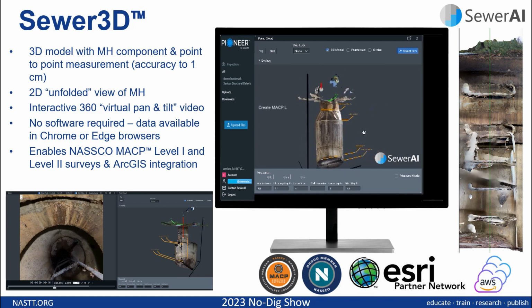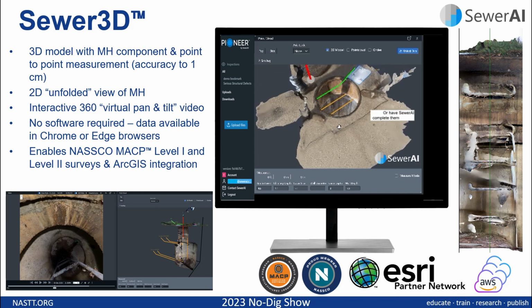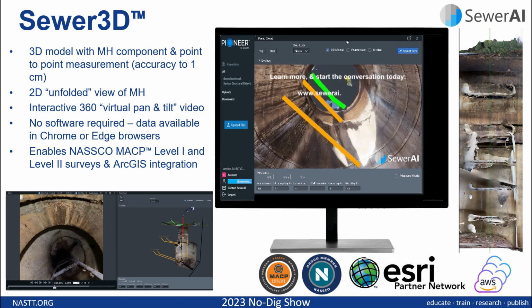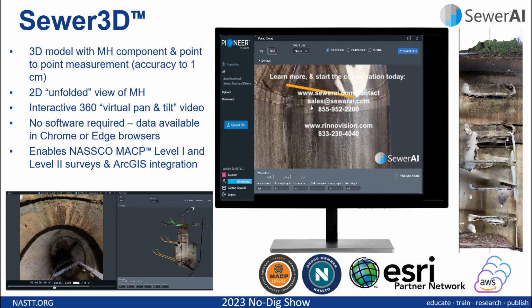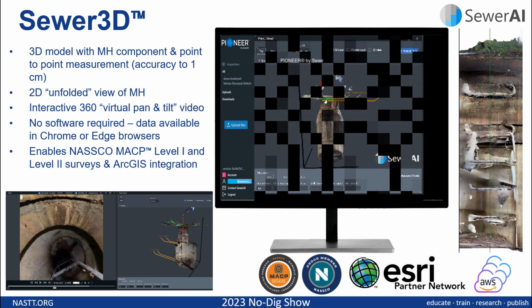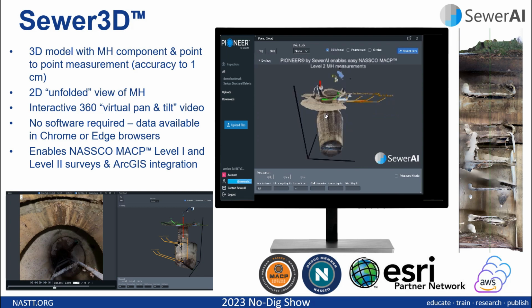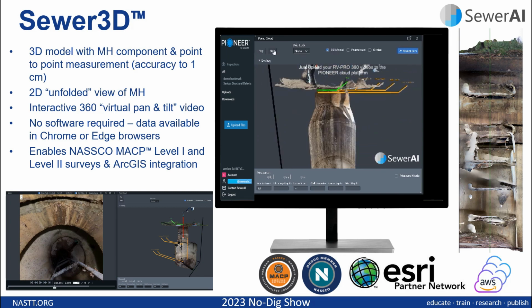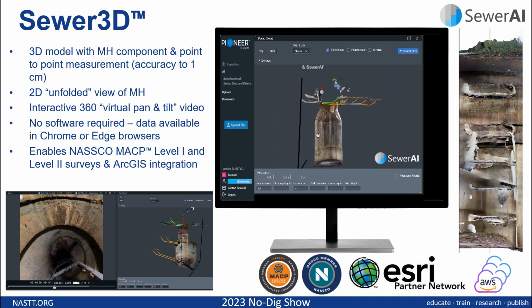The method used to render these 3D models is called photogrammetry. Photogrammetry is the use of advanced mathematics to calculate the position of digital pixels as points in 3D space. Inside the 3D model, one can quickly measure components in the structure, conduct custom point-to-point measurements to an accuracy of 1 centimeter. There's also a 2D unfolded view of the structure, which can also enable vertical measurements and can be useful for identifying connecting pipes or missing bricks, etc.